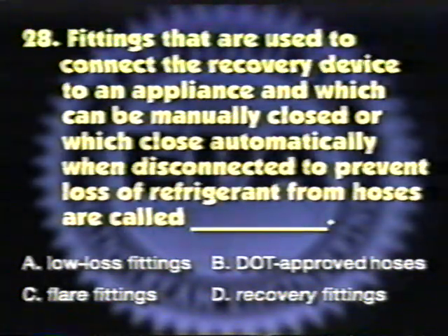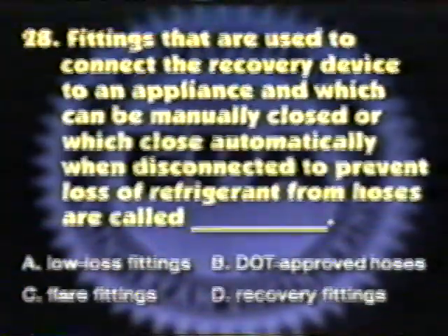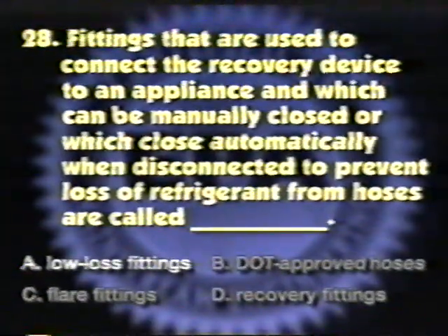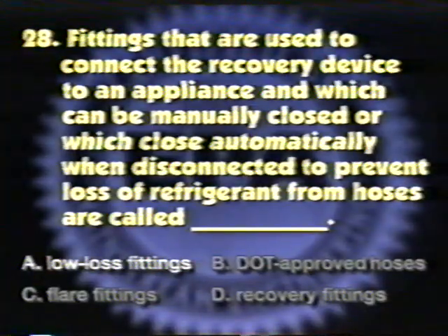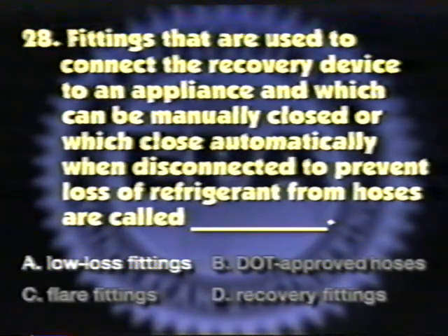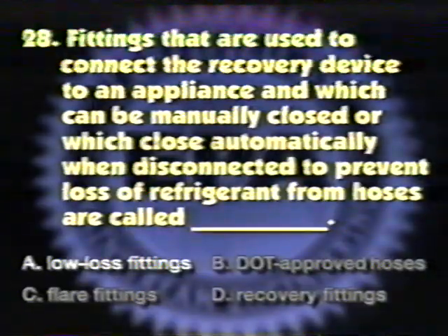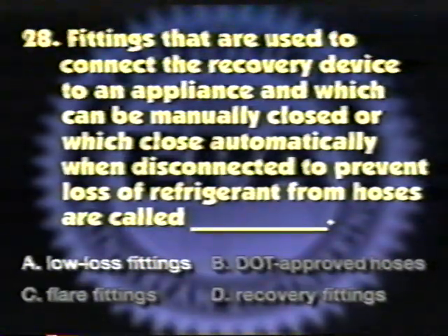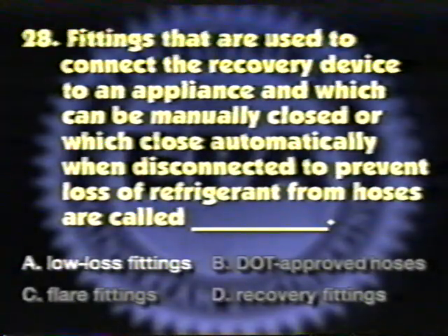Since November 15, 1993, refrigerant recovery devices must be equipped with low-loss fittings, which are fittings that are used to connect the recovery device to an appliance and which can be either manually closed or which close automatically when disconnected to prevent the loss of refrigerant from the hoses. So the correct answer is A. Low-loss fittings.